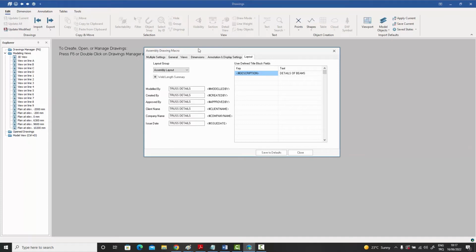What we mean by the layout is how the page will be laid out. So consider this to be an empty page, you could have a material list at the top right corner, you could have a title block at the bottom, and you could have a bolt list just under the material list. And all these definitions would then comprise the layout for that drawing, and we'll talk about the details of that layout when we get to this. But at the moment, all you need to know is that in the layout tab, you can select the layout which you want. Over here, we basically have several fields, and you can add custom fields over here. And whatever you fill, these fields can then be recalled into your title blocks, etc. And we'll talk about those in a second as well.